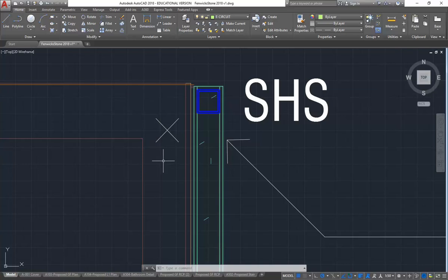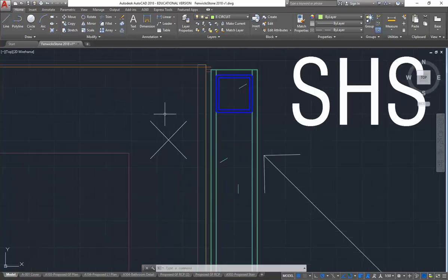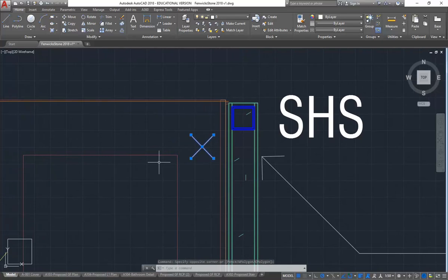It's drawn roughly, but again, if you put a measurement on and it's not appropriate, the electricians are still going to follow that measurement rather than using their own experience and judgment to work something out that might be better. The same goes with the heights; there are standards and conventions that are followed generally. If you're not sure about those things, just put it in roughly, and the electricians and the people who've got experience will do it more precisely, following more established conventions. So again, for construction certificate drawings, I think it's going too far if you put those measurements on.